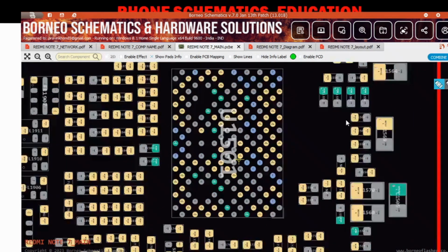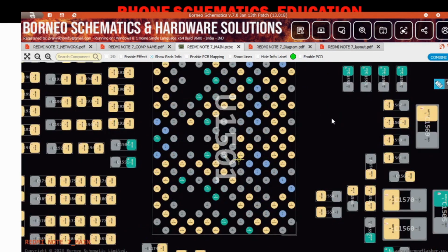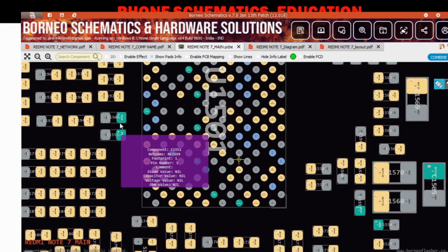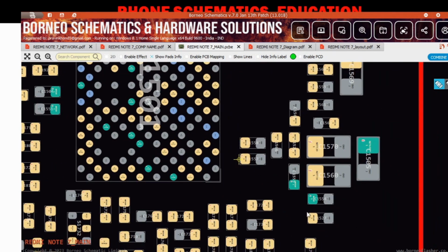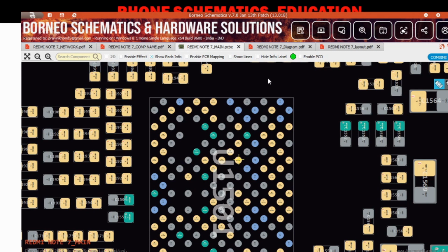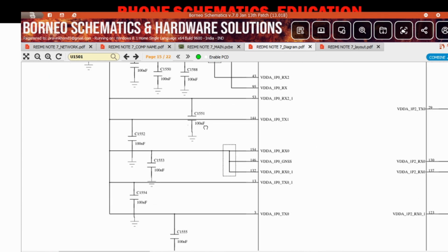So you can see here in the bitmap, these 4 capacitors are also connected with the SDR IC. Also these 2 capacitors, these are filter caps, 2 caps here, right? So 7 capacitors are connected to 12 balls, right? I hope you get my point. Now get back to the schematic for another. I hope you get this point.